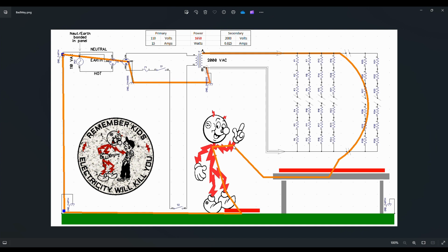Imagine a damp shirt sleeve here, touching this table for just a second, and you notice our operator here has got one foot on a pad, which doesn't guarantee anything. Some of these pads I've seen with holes big enough that you could drive a ton of electrons through, but in this case he's got his foot directly on the ground, so the path might or might not go this way. It might go this way through this foot, or it might go up the arm, through the torso, through both feet simultaneously.